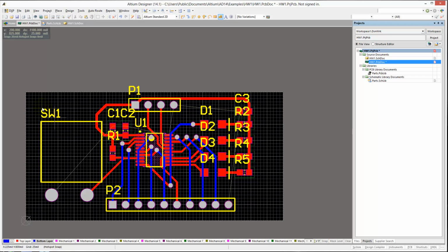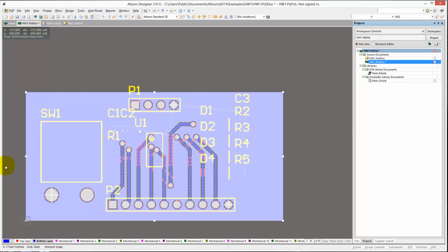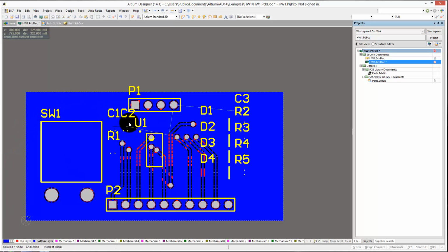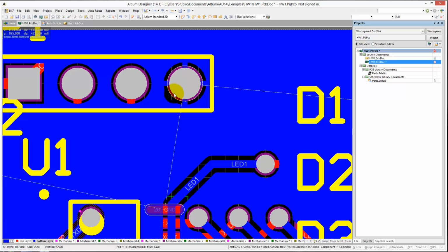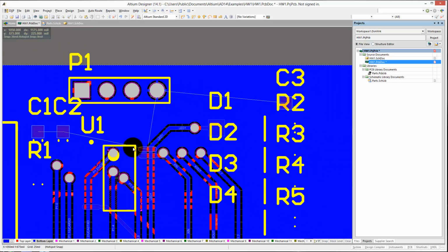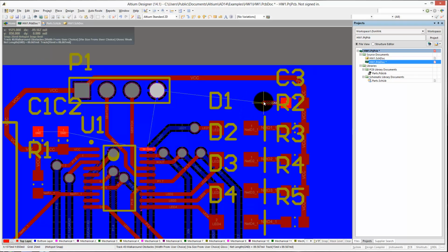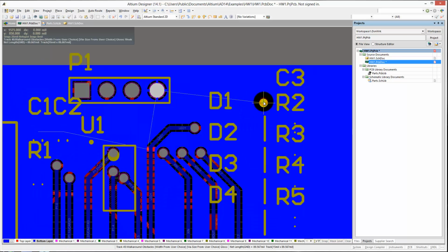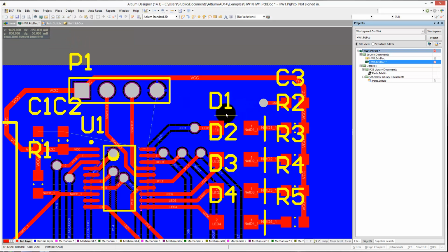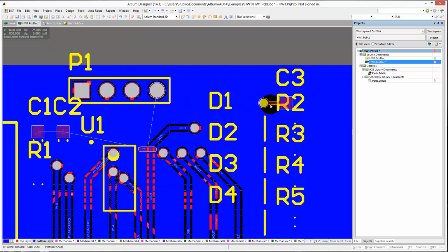Once you click OK, you can actually draw a polygon as large as your PCB. And what it will be is this will be one solid copper pour at the bottom layer that's all connected to ground. And will be connected to these particular devices. So you can see that with these, what's called a thermal relief, it's connected to this particular ground pin. And now we need to go to the top pour, PT again. We want to route from this one here out and go into the ground layer. As you can see, this made a full connection into that plane itself.